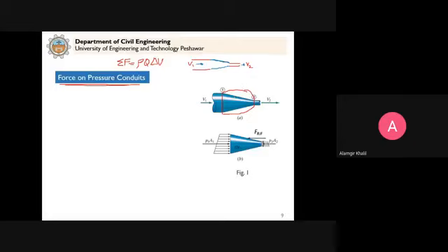So now to calculate the forces, clear, we consider the case of horizontal flow to the right on the reducer. Why do we consider the horizontal flow? So that we neglect the weight of the fluid. The free body diagram for the forces is shown here. So this is the control volume. This we considered as the control volume. Now in this control volume, we have this force as the acting force of the reducer on the fluid.